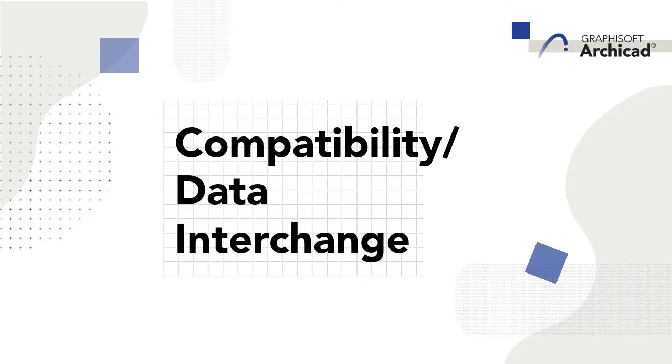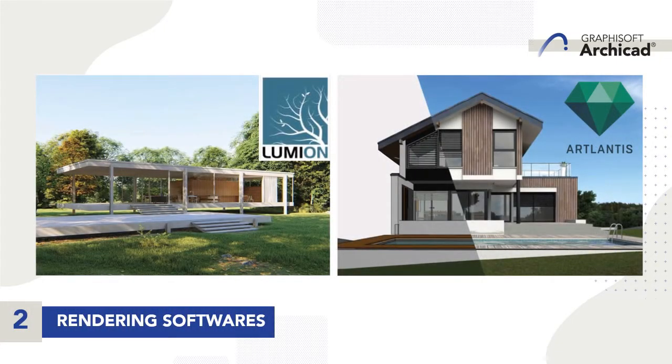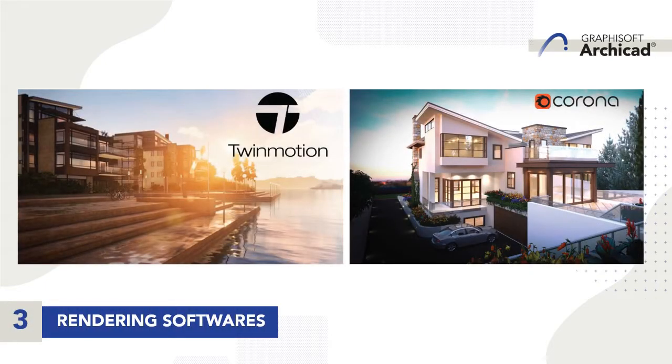Next, we'll discuss the compatibility and data interchange involved in the ArchiCAD software. With ArchiCAD, you are able to import and export DWG, DXF, IFC, and BCF files interchangeably. You are also able to use rendering software such as Lumion and Artlantis to create high-quality renders seamlessly, as well as Twinmotion. ArchiCAD users are provided with a special privilege to use Twinmotion for free. However, for Corona, even though it is yet to be fully compatible with ArchiCAD, Corona developers have recently announced that they are currently working on a new plugin to support ArchiCAD so that you can render with Corona seamlessly.